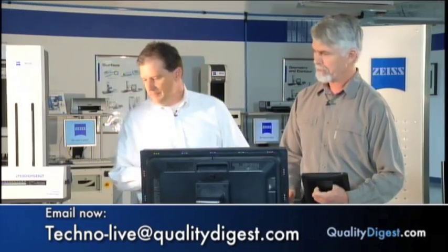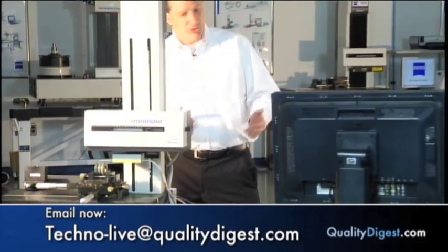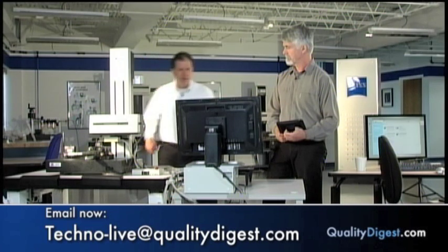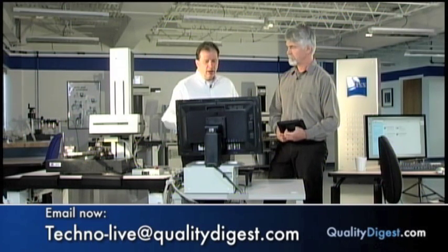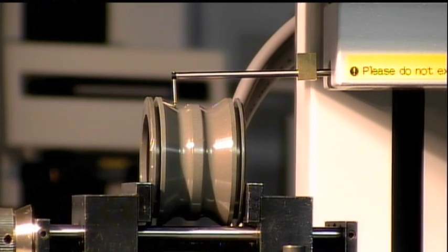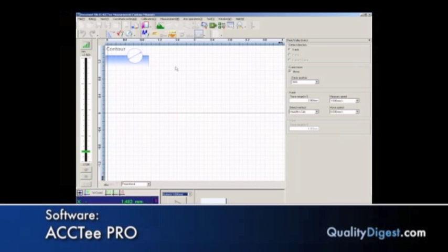Absolutely. So the first thing I want to do is make sure that my stylus is located where I'd like to start my program, which I'll do with the joystick. Then a really neat tool in this software is called the Peak and Valley tool. This allows me to find the part, or find a feature on the part. The feature we're going to find on this part is a valley. This is an arc shape, and we're going to locate the stylus at the bottom of it so that we know where the part is.